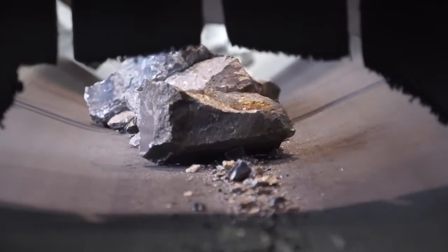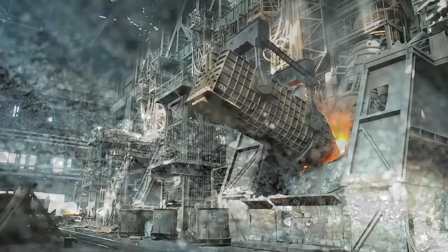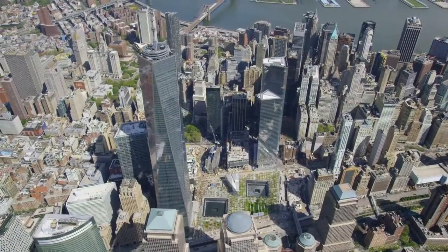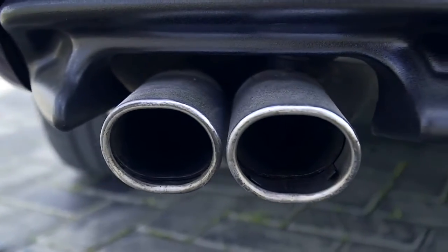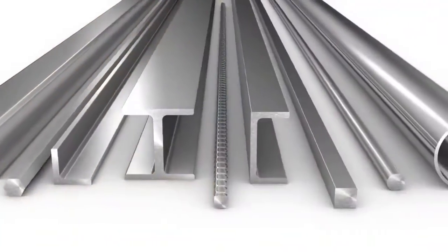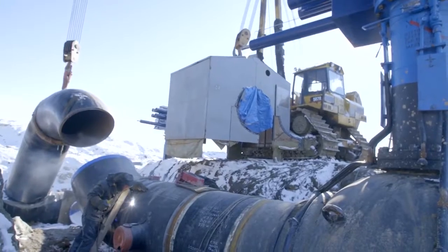Niobium is a uniquely versatile element that has become indispensable as a microalloying element in many high-strength, low-alloy steels, for example in line pipe and structural applications. It is also an essential addition in a variety of stainless steels. Very modest additions of niobium can impart strength and toughness to steels and also improve weldability.